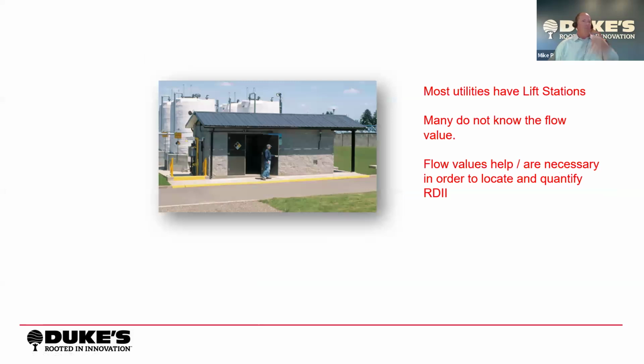So yes, most utilities have lift stations. However, many that I've worked with do not know the flow values. There are instruments that can produce that, namely an electromagnetic flow meter. It's actually pretty uncommon. So, most utilities are getting some kind of data out, but they don't know the flow value. They may know that the pumps run 30% longer during an X rain event, but they have no idea what the flow values are.